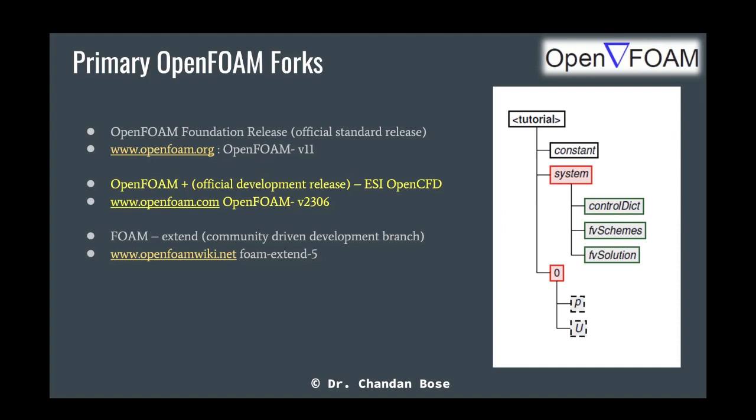All right, so to do that, we use mapFieldsDict, which can map the field variables from one simulation folder to another simulation folder. Is that clear?